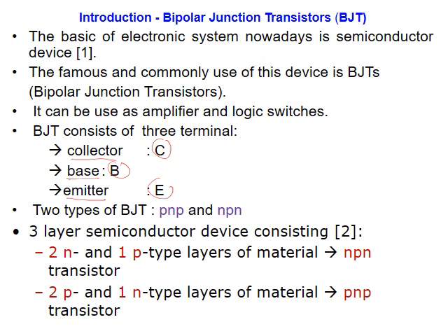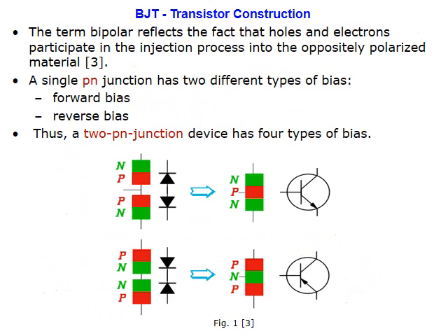There are two different types of BJT, bipolar junction transistor: PNP and NPN. You remember the layers P and N, positive layer and negative layer. We either put two N layers and one P, we get NPN, or we have two P and one N, we have PNP. I don't need to repeat the same discussion for both. I will focus on NPN, otherwise PNP is the same, just the signs and directions are different.